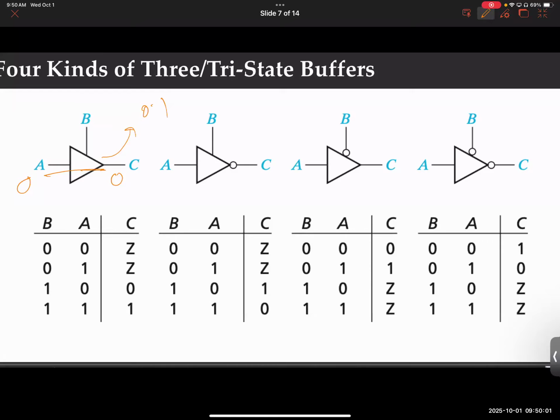A floating node can be easily hampered or changed by environmental aberration, fluctuations, interference. But a node that is being driven cannot be changed that way. So you're basically letting the node do whatever it wants. That's what floating node means. That's what high impedance means.